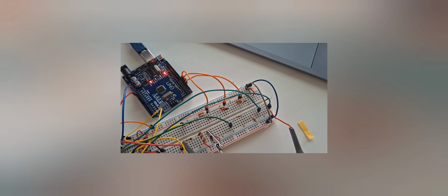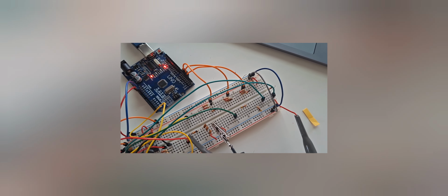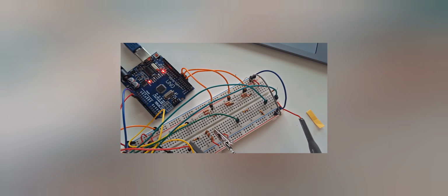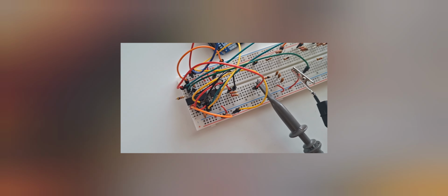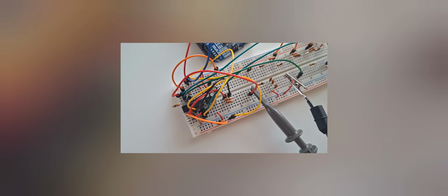This is the physical circuit on the breadboard. The 3 orange wires are the 3 logic inputs that we use. I coded them to follow a particular sequence that allows me to mimic a sine wave. This is the op-amp part of the circuit, which has both the voltage adder and the digital to analog converter bit.